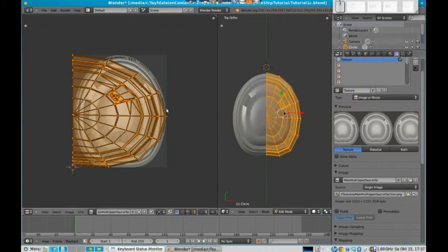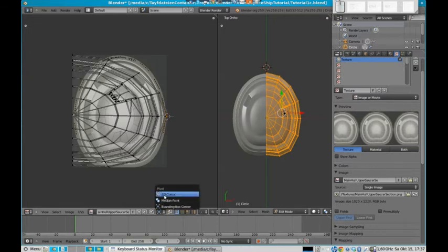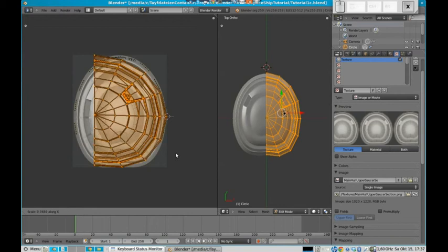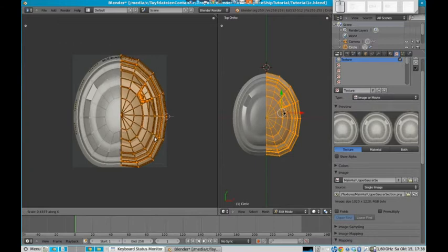So now I want to, that's because of the mirroring. Without the mirroring, the UV mapping would be already almost perfect, but I don't want to apply the mirroring right now, so I will just correct it manually. Let's set our 3D cursor to this position here, exactly like we did in the 3D view, by pressing Shift S and say cursor to selected. And now here we have something similar, just select the 2D cursor as our pivot point, select all vertices and scale it down, but just via the x-axis. Like that, like that, like that. Whoa, whoa, whoa. I made a mistake when doing the model, I realize right now, and that's it.